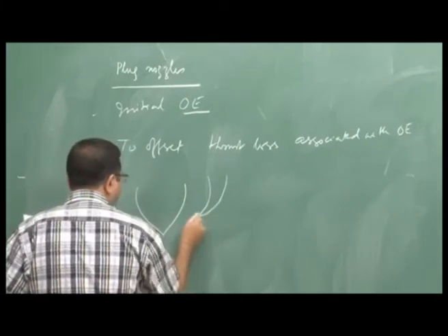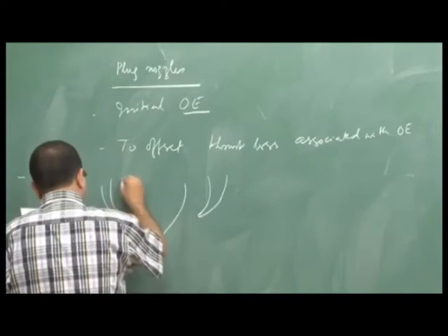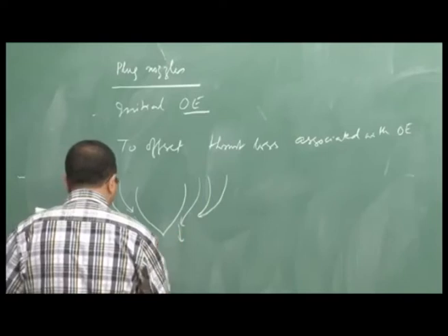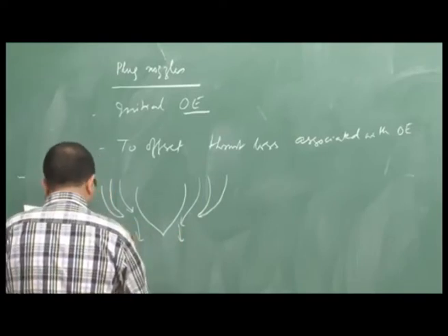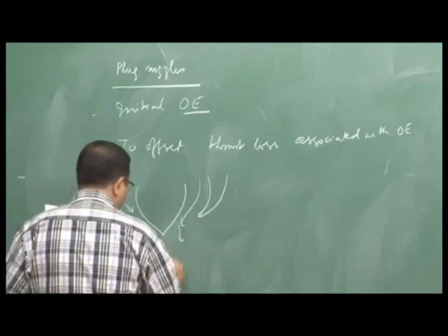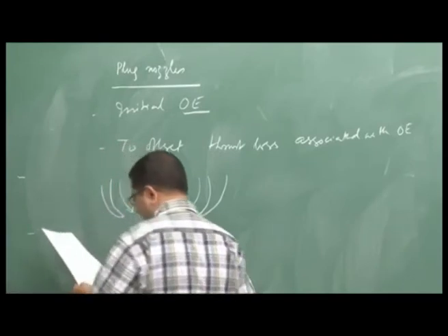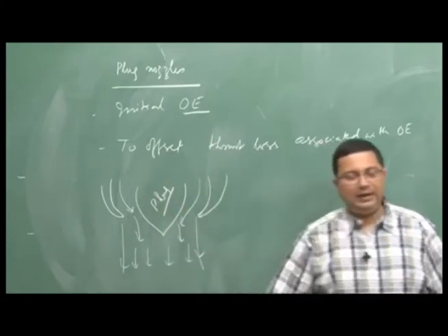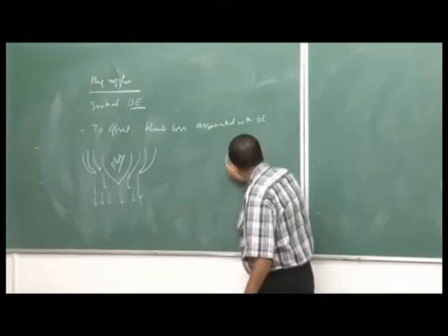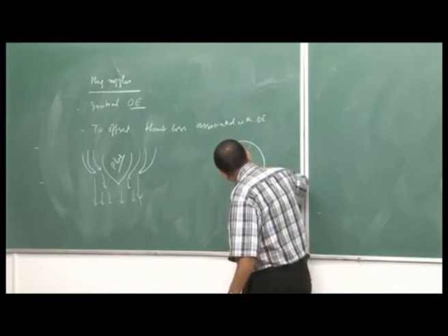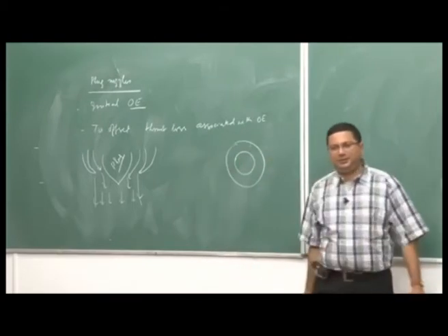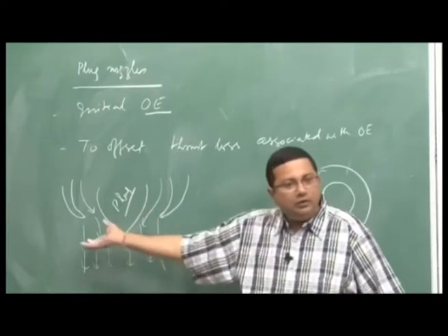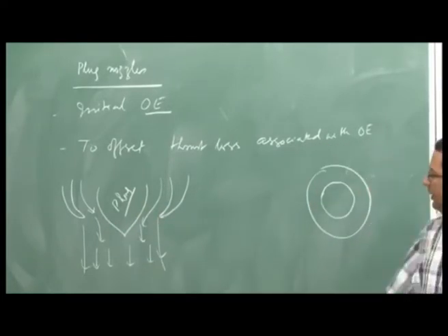Okay. This is a plug, the flow comes here, goes uniformly outside from here. This is called a plug. At the exit of the nozzle, if I look from the front, we have a body like this. This is called a plug. Of course, this body is contoured, and this contour can also be obtained using method of characteristics.